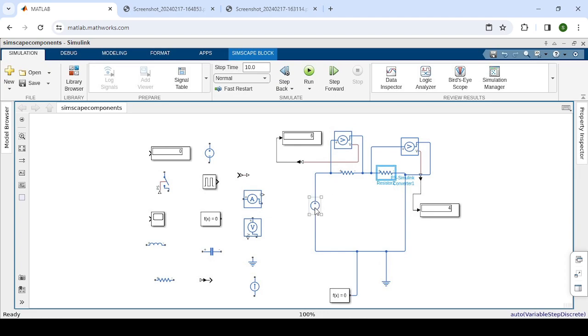So from the voltage divider theorem, the voltage across the 6 ohm resistor is going to be 6 divided by the equivalent resistance, which is 10. So 6 over 10 times 10, which is the source voltage, and that's 6 volts, as expected. Here too we have 4 divided by 10 times 10, and that is 4 volts.